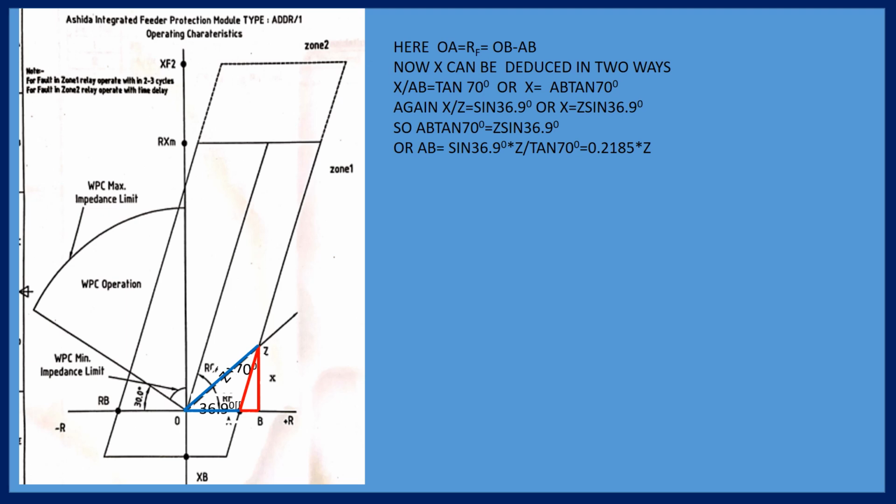But most important is the differential relay. With the bushing CT we are connecting it, and its polarity is given. So you must connect in such a way that the relay should not get additive current. It is differential. It will measure the difference of the current, and the currents will be opposite.